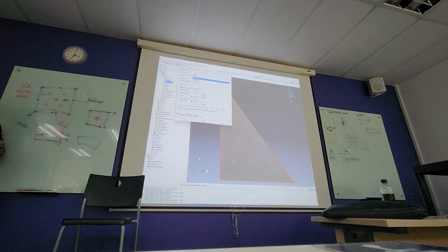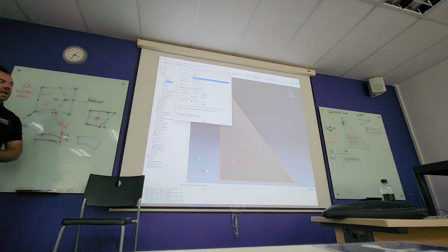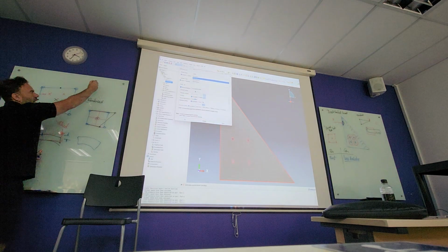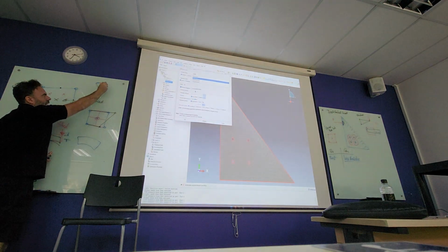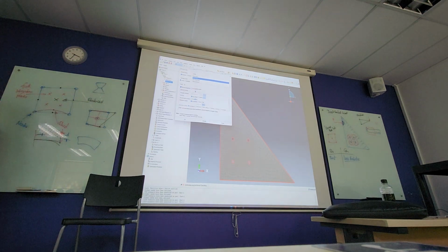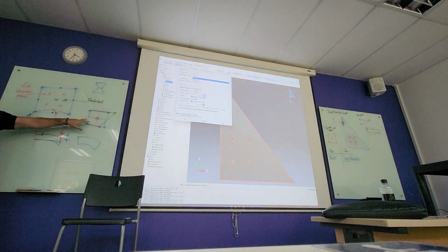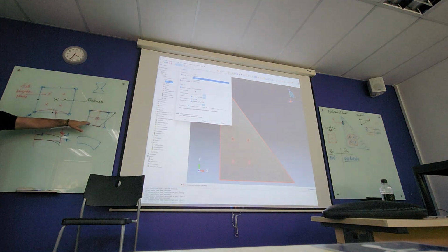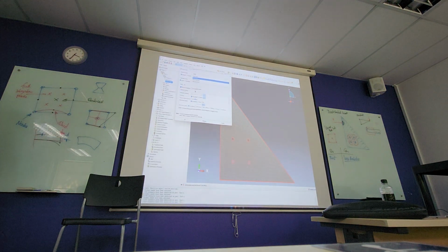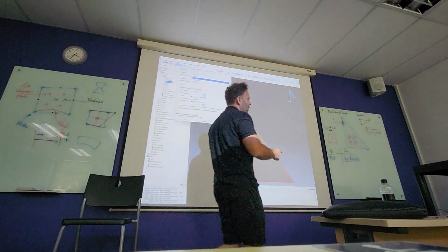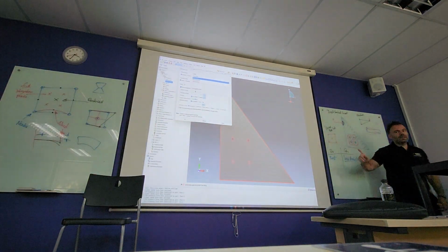And you got a situation of so-called hourglass. And you observe that by having elements deforming like this, like an hourglass, because it sort of cascades. So basically that's where the term comes from, hourglass. What it essentially says is that there's no deformation. Something called strain energy is zero. And in reality it should not be. So if you are using those, that is a problem.